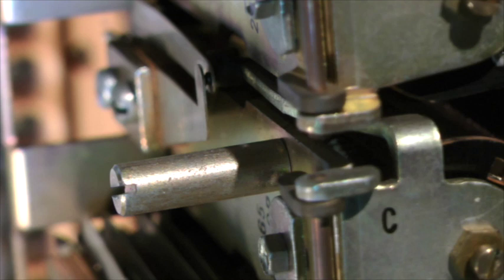The C relay controls the vertical and rotary stepping functions. It quickly operates and releases via its secondary winding to energize and de-energize the vertical magnets and the rotary magnets to accomplish vertical and rotary stepping. When the connection to the first selector has been established, the C relay releases and remains released for the duration of the call.